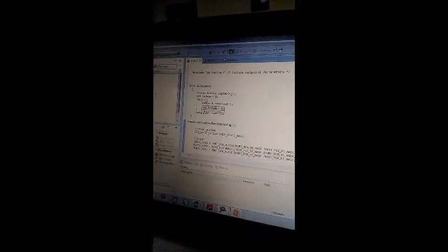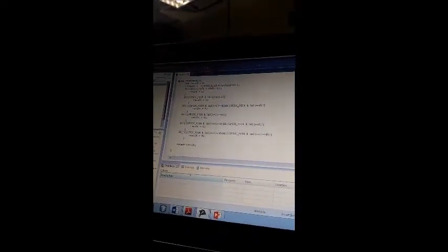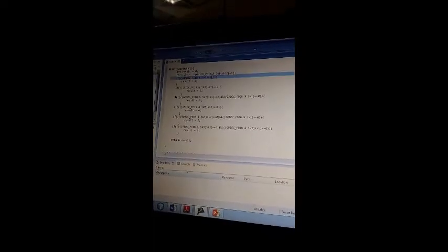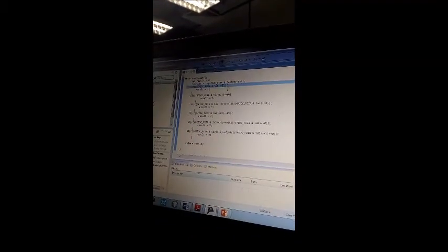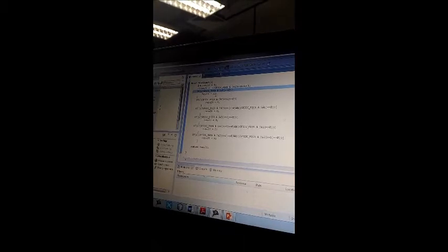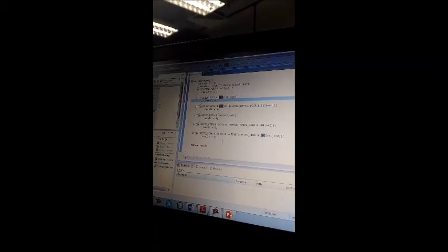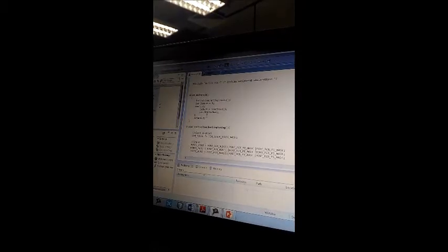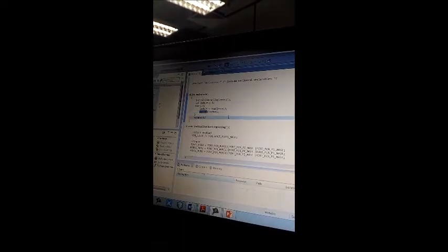So after that, we will have a read input function to give us an LED number. The read input function is like this. First we declare the result as 0, and we check each of the switches. So by using the combination just now, and by providing the switch with a ground, in this case we say if switch 1 is 0, then the result is 1, switch 2 is 0, the result is 2, and so on, 1 to 6. Returning the result back to our main function, passing the result as an LED number into our setLED, and this is where the magic works.